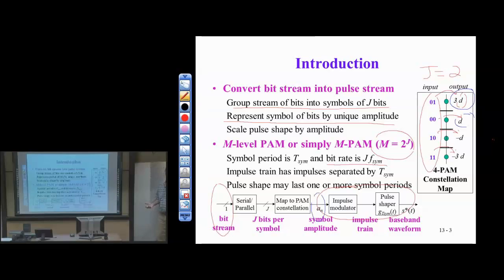Well, in communication systems, we don't get to use all possible bandwidth. We're limited to some band. So we're going to follow this with an analog continuous time filter, but this filter will be finite impulse response, which is a little unusual for an analog continuous time filter, but they do exist. This is a tapped delay line, or something like it. And so we're going to do a pulse shaping here. This is the theory side. We'll get to an implementation that we'll do in lab in just a second.